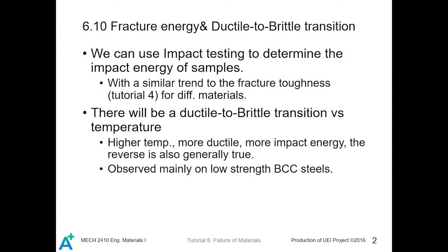Fracture energy is the energy required in impact testing to break a small sample, and therefore we can use impact testing to determine the impact energy of a sample. Actually, such energy is comparable with the fracture toughness for different materials, which have a similar trend.